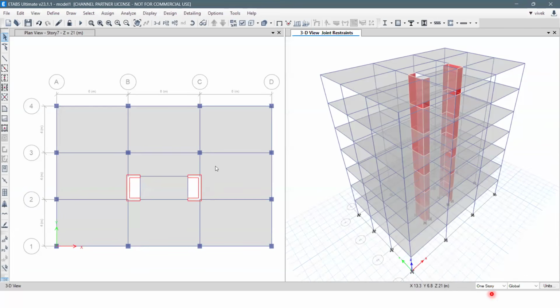So typically the walls do not require meshing, as we are interested in the forces at the top and bottom of this wall, where they are significant in these building systems. So that is a general recommendation. But if you want to mesh the walls, there are two ways.